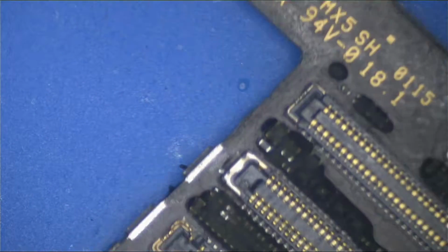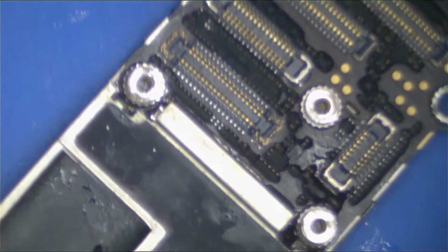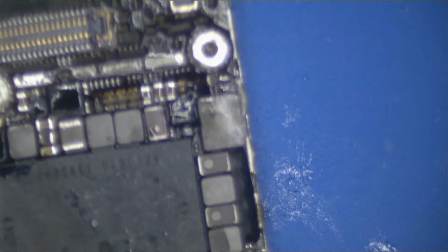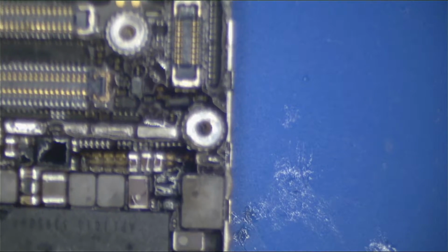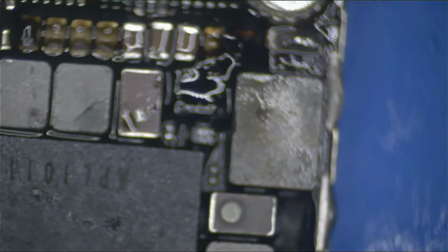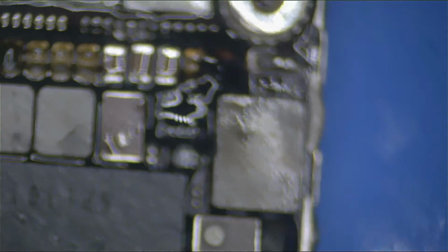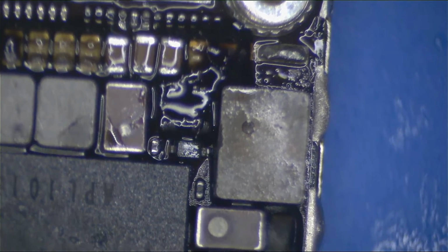So I'm going to take this board out, and we're going to go ahead and pull the shield off. Turn on the air filter. Okay, so we got the shields removed now. The first step here is, actually you can see that someone has already replaced one of the backlight caps and the diode before me. This was taken to another shop before I got it, and I guess they couldn't figure out why it only had partial backlight afterwards, so now it's here.